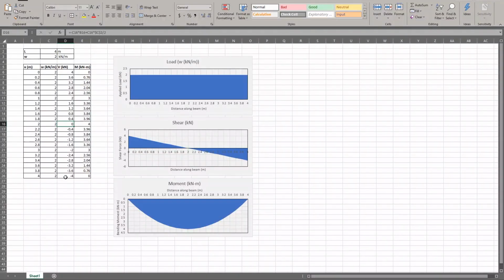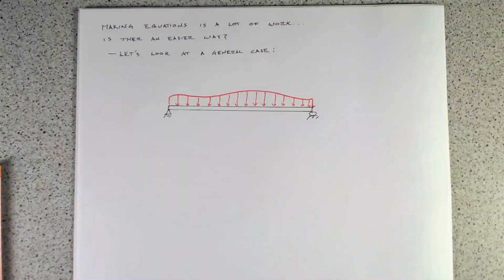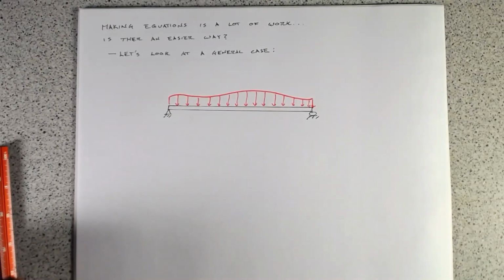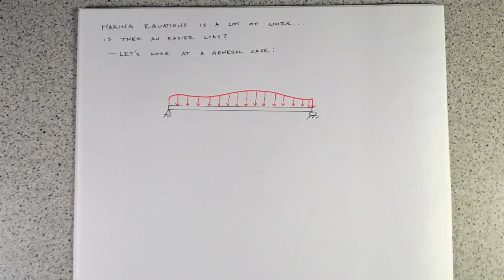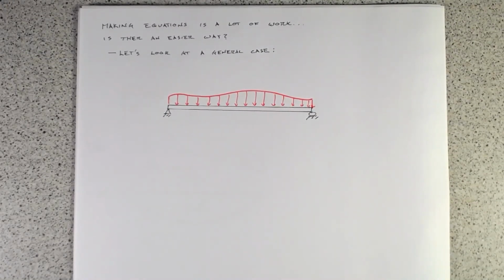So if we're going to do that, we need to have some tools to get there, such that we don't have to go through and brute force and do a free body diagram every time. Knowing that we always can is important, and it means that if we're ever stuck, we can use free body diagrams to get us out of that jam. But let's see, is there anything that we have about these shear and bending moment diagrams and some of the relationships that we might have seen here, from where we had sort of constant load, linear shear, parabolic moment that we might be able to exploit.